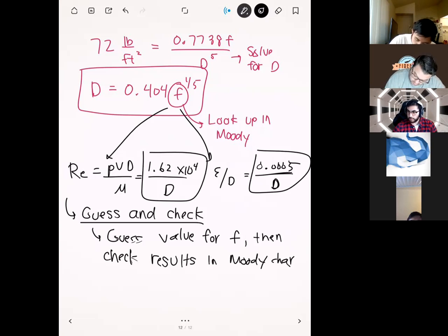We start with what I call a reasonable figure for F, plug it in, and check to see if we get the same friction factor out. If they're the same, then we're good and can finish guessing. If not, we keep trying with a different guess. I'll walk you through that process on the next page.